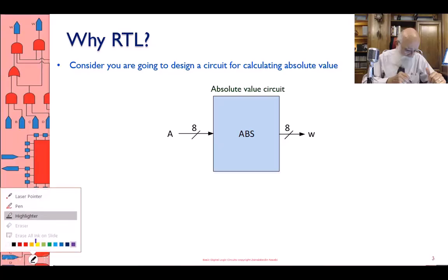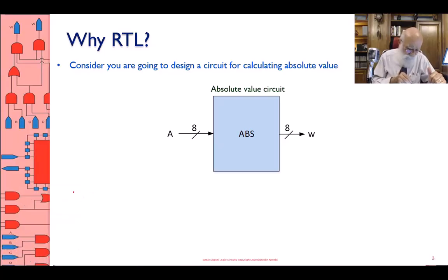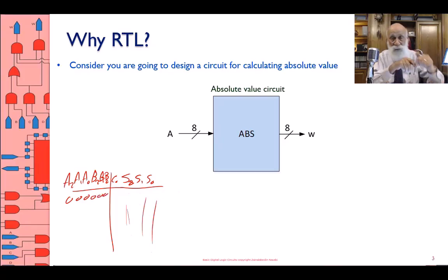And if, for example, we need to build a 3-bit adder, A2, A1, A0, B2, B1, B0, the output will be sum 3, sum 2, sum 1, sum 0, and then carry out. And then we can start with 0, 0, 0, 0, 0, 0, and then just write down the results. And then we have 4 outputs, each of them requiring a 6 variable Karnaugh map.